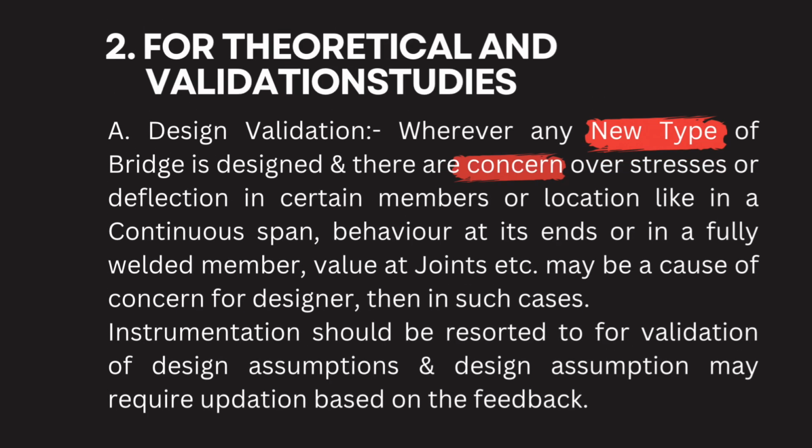Number 2 reason is for theoretical studies and validation studies. In this category, instrumentation is warranted for following cases. A. Design validation. Wherever any new type of bridge is designed, and there are concern over stresses or deflection in certain members or location, like in a continuous span, or in a fully welded member, etc. In such cases, instrumentation should be resorted to for validation of design assumptions, and design assumption may require updation based